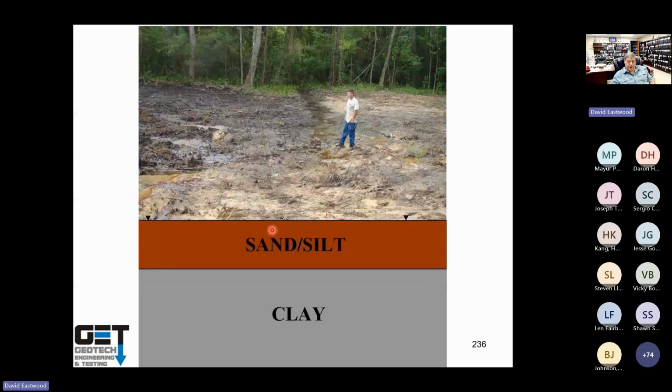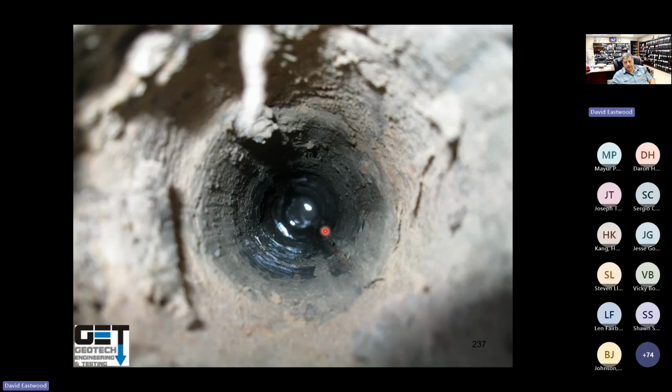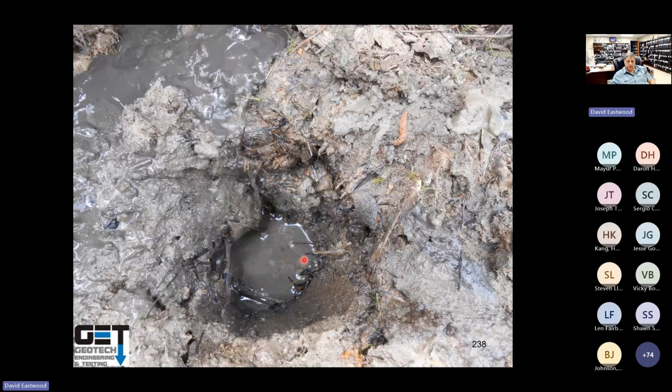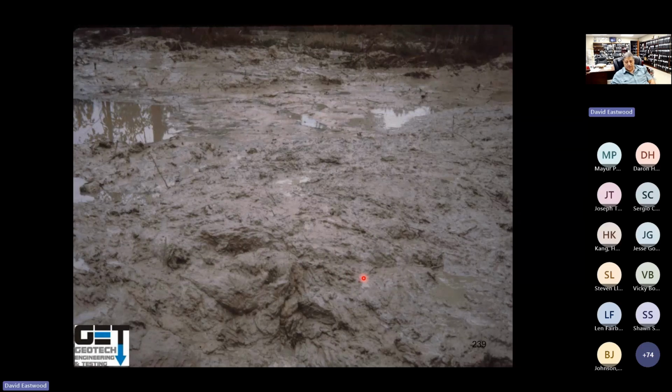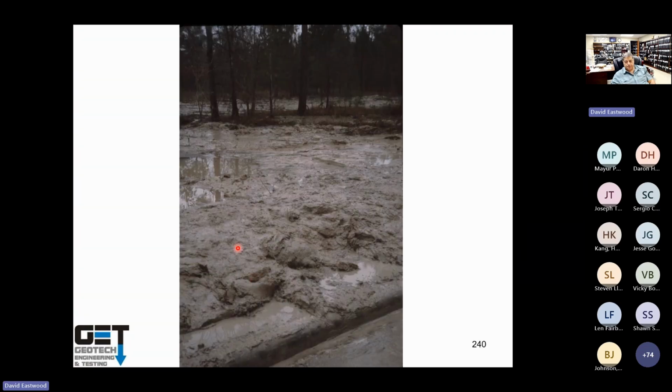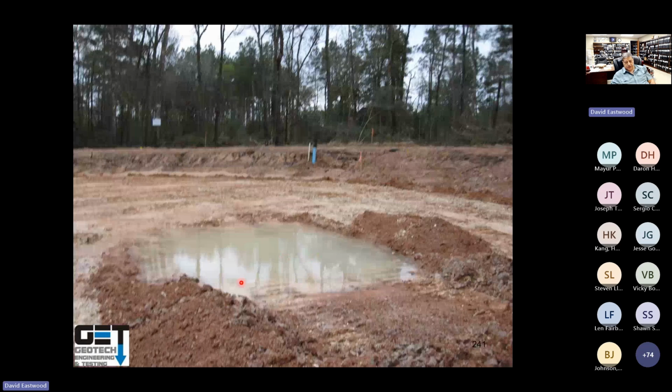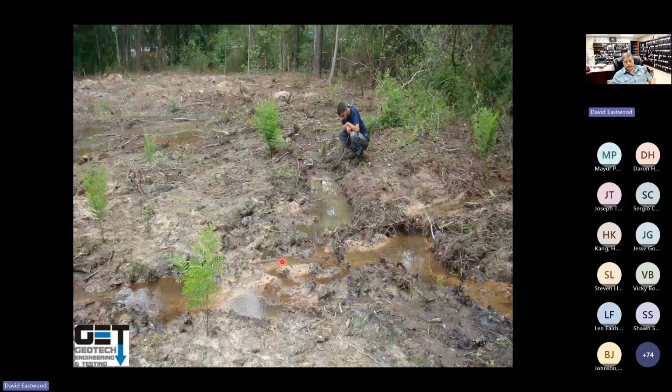Fresh water table, if you're out there in Katy, parts of West Harris County, you got these sandy soils. Or you go out there, parts of Waller County, we have a lot of perched water in Waller County. You got these sandy soils over clay, that water just sits on top of the clay. Regular water table, 20 feet, perched water table, about 6 inches. You remove the grass and weeds, and the soil turns into mush. You take the trees out. So water just sits in there, can't penetrate it.